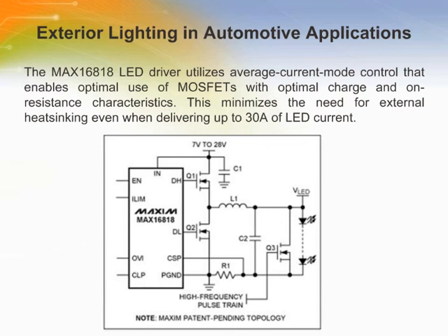Exterior lighting applications must typically turn on fast or switch brightness instantaneously. To achieve this, the MAX16818 is the first LED driver that uses Maxim's average current mode control technology for fast LED current transients of up to 20 amps per microsecond.